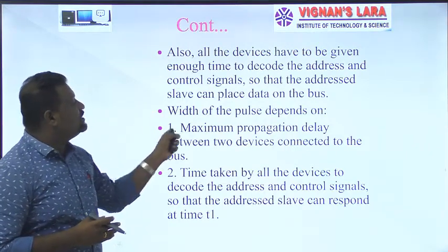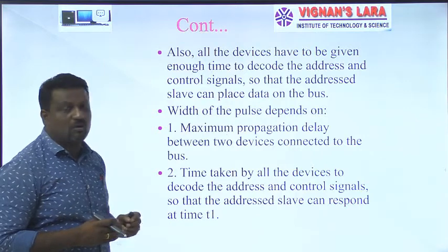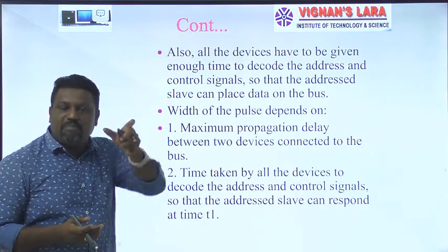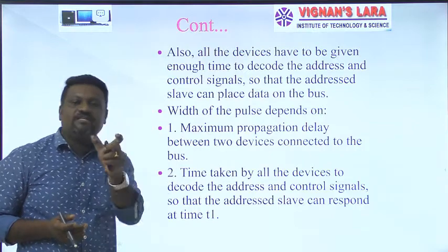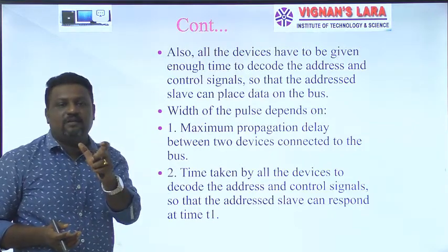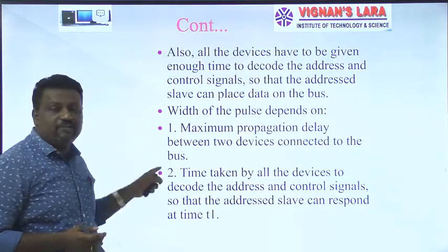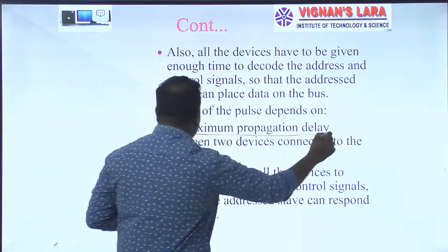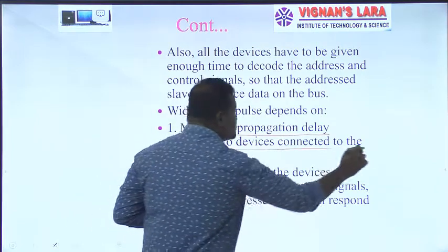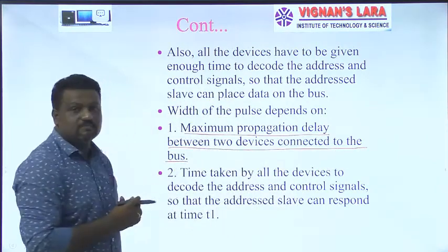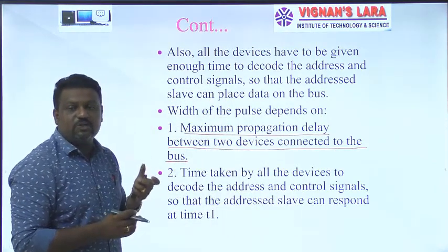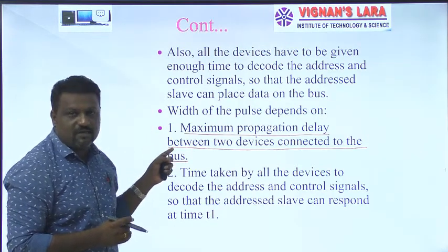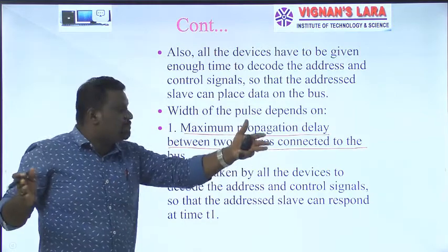The width of the pulse depends on the clock pulse width, which is your master signal, your synchronizing signal, your bus signal. That width depends on different parameters. The first parameter is the maximum propagation delay between two devices connected to the bus.